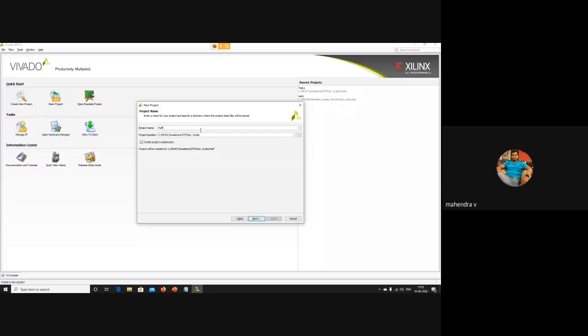Half adder, underscore adder. This is the user defined name. That is an identifier. We need to follow those rules strictly. These names should not start with a number or underscore, and we have to use only alphanumeric characters and underscores for the names.